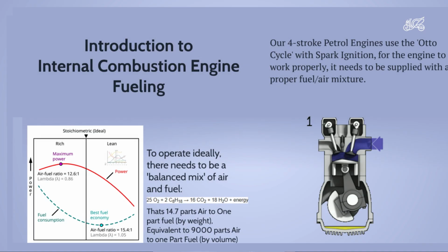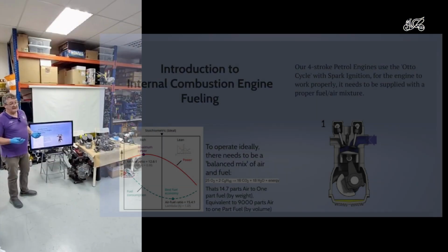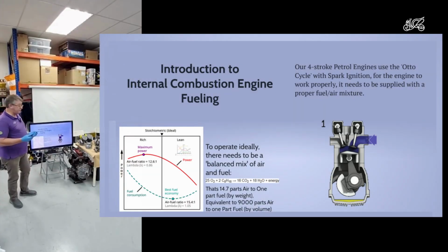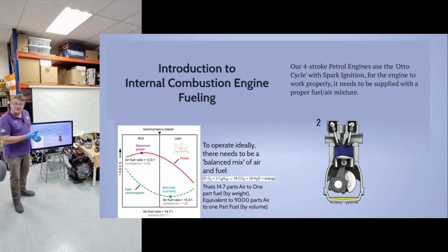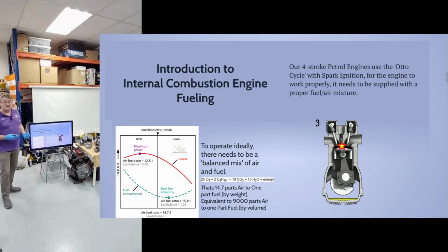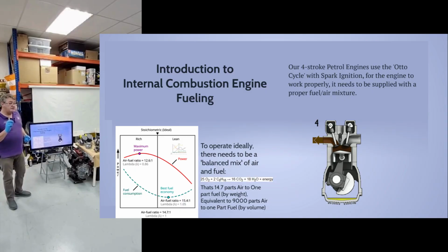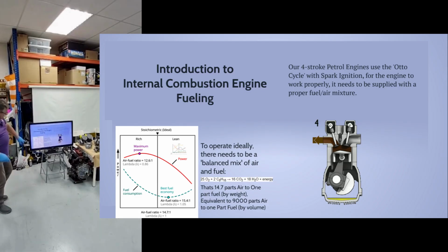So in our combustion engine, we're sucking in a fuel air mixture and we're exploding it. And to make it extra difficult, this engine isn't running at one speed, right? If it were running at one speed, the airflow would be constant, and you could then set up even something like a drip feed thing and it would work, right? But the issue is the engine speed's changing wildly, the airflow is changing wildly, and we need to somehow get the right fuel air mixture.